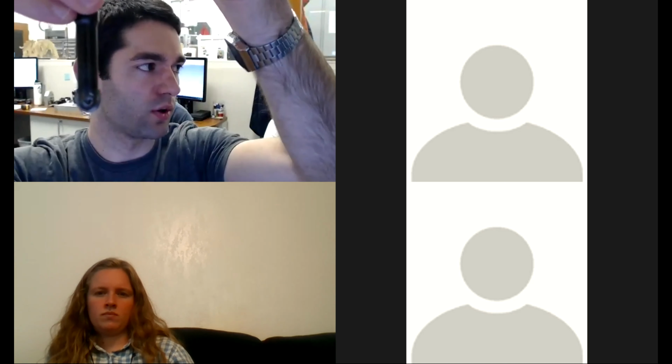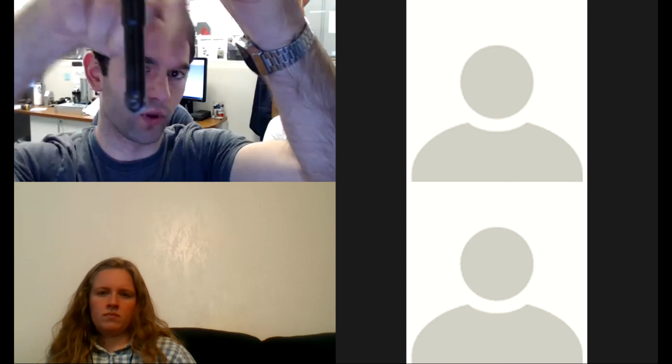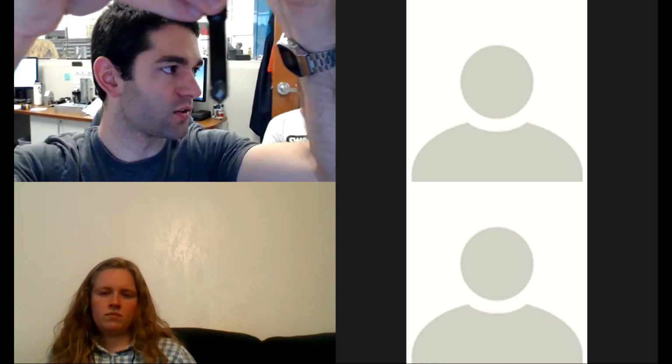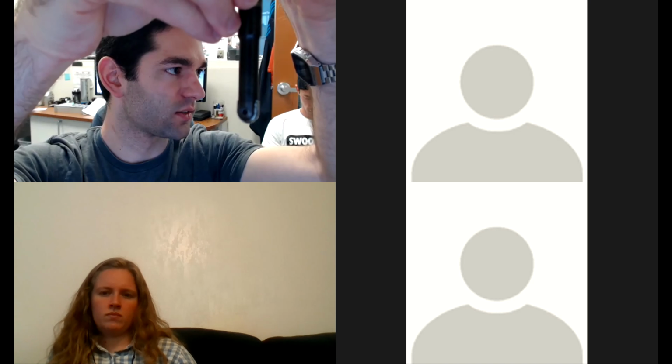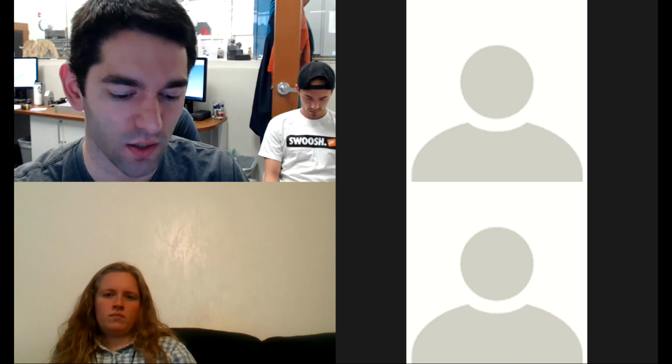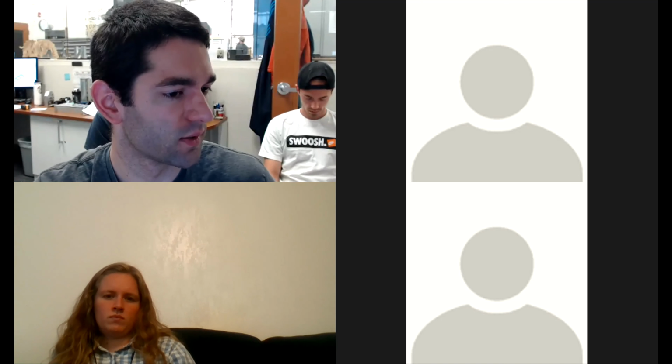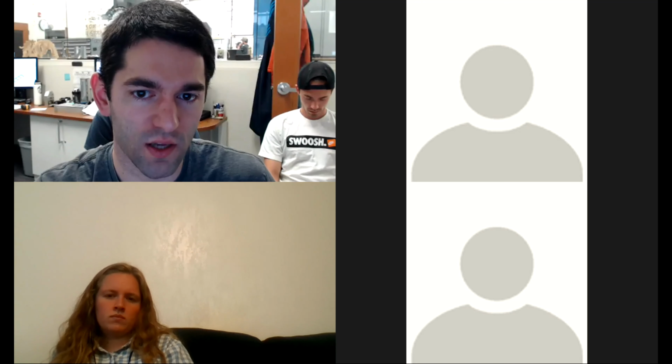And so chip load is how far it moves from when one tooth cuts to the next. Does that make sense? Yeah. And that translates directly into the thickness of the chip that you're shaving off. So that's one parameter that, regardless of your spindle speed, you generally want to keep the same.